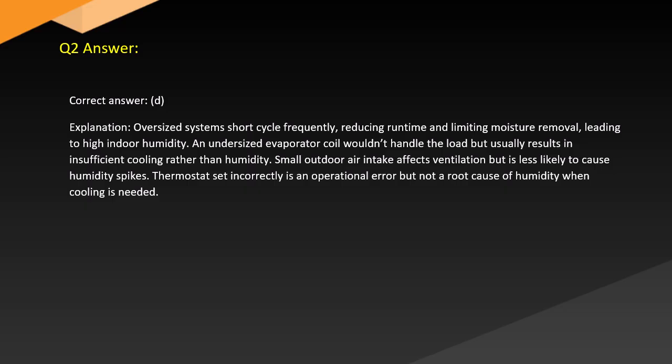A small outdoor air intake affects ventilation but is less likely to cause humidity spikes. A thermostat set incorrectly is an operational error but not the root cause of humidity and cooling needs.